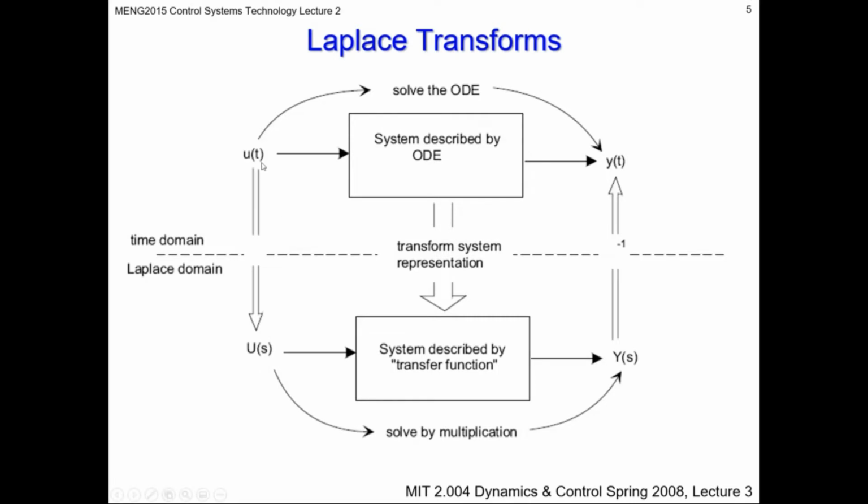To do that, we have to transform our input into an equivalent Laplace domain input. But we also, and this is the more tricky bit, have to transform our system, described by ordinary differential equations, into a system described by algebraic equations, which we call a transfer function.